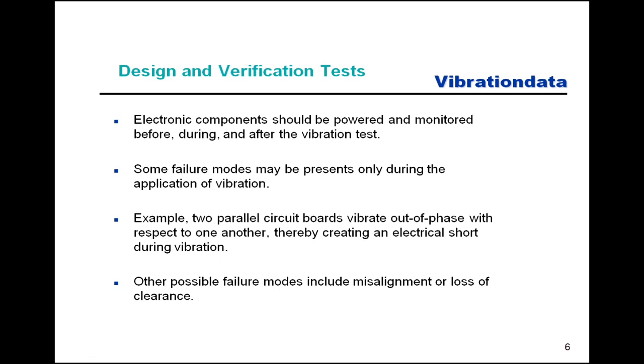So certainly if the component must perform its function during vibration, it should be powered and monitored during the vibration test. That is, if it must function in the field environment, under field vibration environment conditions. I think another good reason to do this is, let's say you've got a 1 hour per axis long test on the component, and something happens, one of the lead wires breaks 5 seconds into the test.